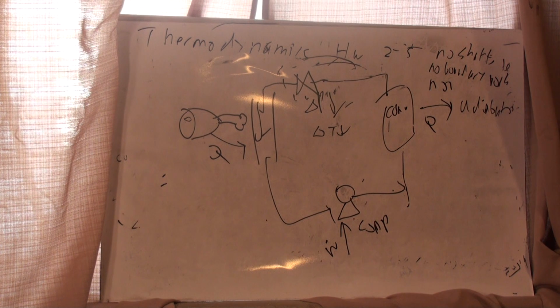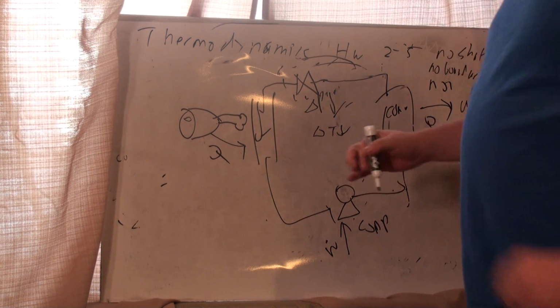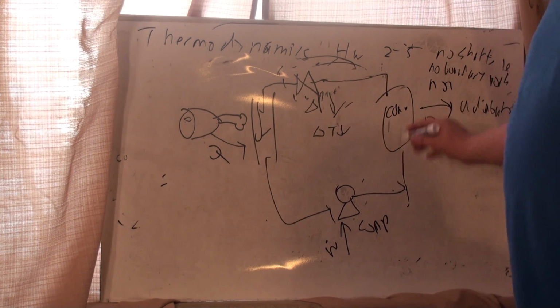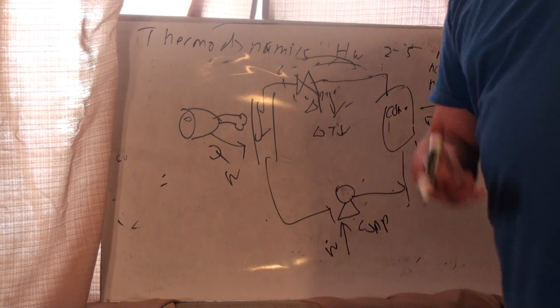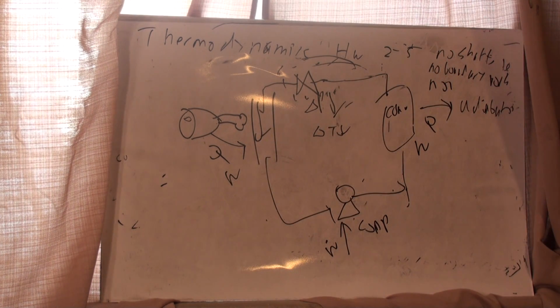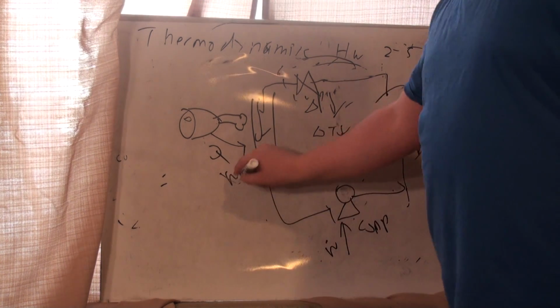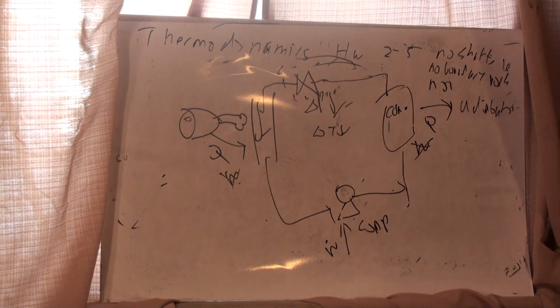Okay. Let's see here, what does it say? I think, from the diagram of this process, draw where things are adiabatic, where heat is flowing from to, and where the work is being done on or by the system. Okay, so there's definitely heat transfer going on here, but there's no work here. It's just happening. Okay, other than flow work, but we're never going to account for flow work. Okay, not explicitly. So no work there, no work there. There's definitely work here, and it's definitely being done on the system.